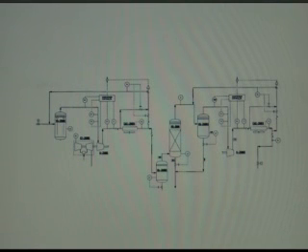And unbeknownst to him, up at the main process control system, the DCS, there was a programmer working on a completely different system, entering code in and trying to debug it. And unfortunately, he entered in a wrong line of code by accidentally typing it wrong, and he swung that isolation valve open. Well, this entire loop, volume-wise, is pretty large, and it's at atmospheric pressure.